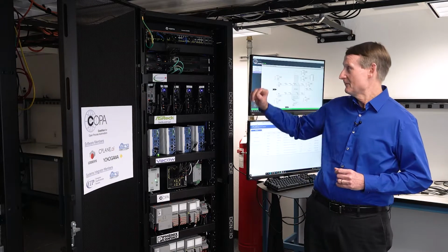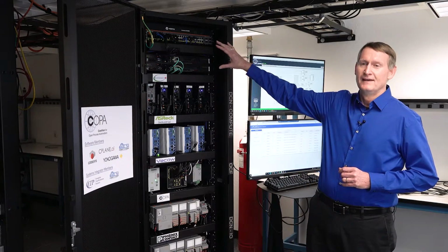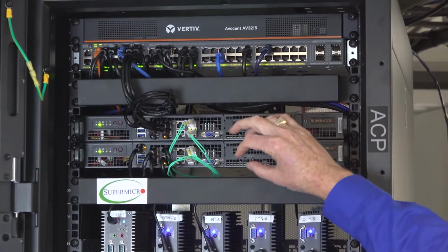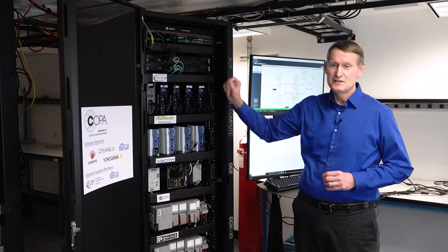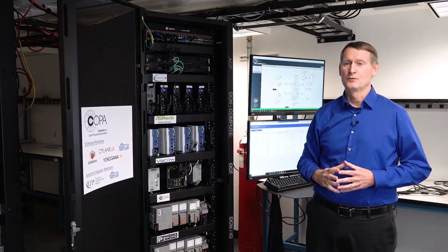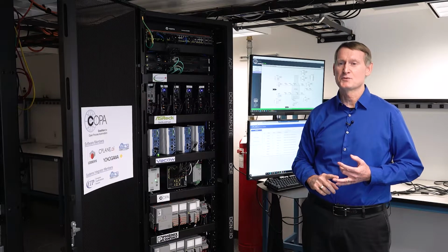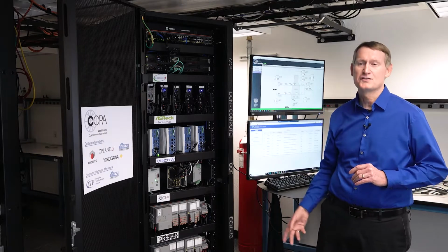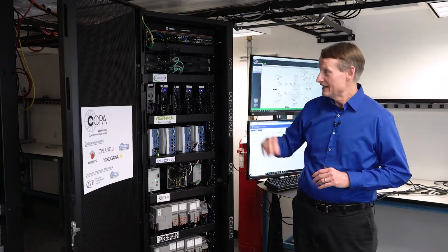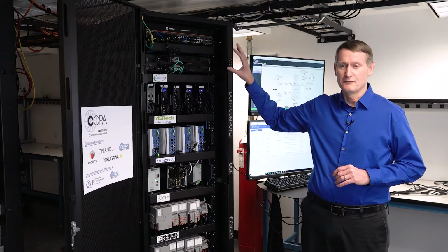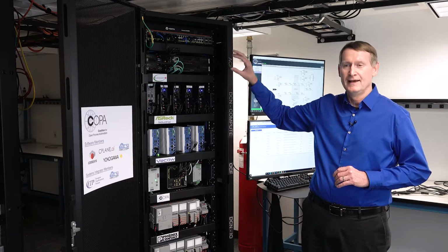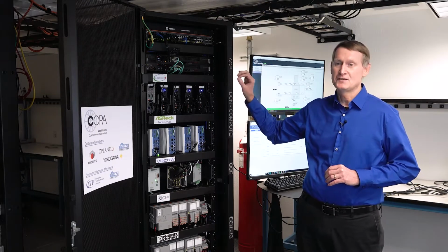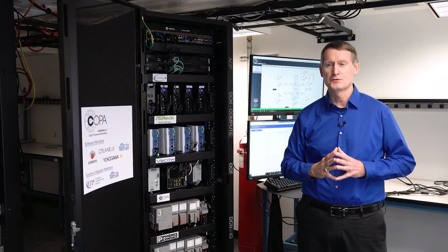All right, so let me get to the top, and that's the advanced control platform. And here we have 2 data center class computers from Supermicro. Now, these host a lot of the management software, HMI, Historian, Systems Management, orchestration, other applications, everything that you need to operate, monitor, and manage the entire system. Now, the ACP is a powerful and flexible platform for advanced control strategies, for monitoring, and for AI applications as well. And the fact that it has high availability and low latency means it's a powerful foundation for digital transformation applications.